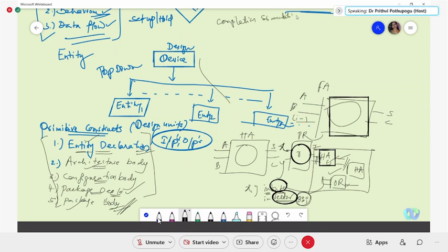So the step of compilation is that you will be checking syntactically whether your writing is proper, or whether your declarations are properly connected, or any declared signal is not connected, not defined, or it is kept vacant. All this checking will be done by the compiler, the compilation portion. After everything is properly defined, linked, and elaborated, then the netlist will be generated.